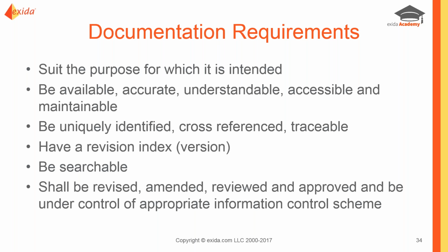The standard does not specifically state what is required in terms of documentation, but you can apply the same thought process that goes into requirements on a PSM covered process by OSHA CFR 1910.119. What is the technology related to the process? What was our basis for doing the risk management?